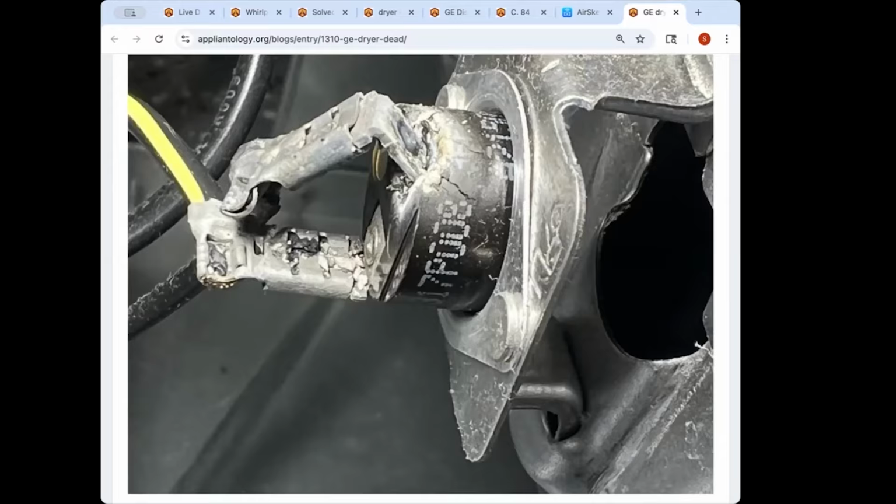And then back to the airflow. I think I have another blog post, interesting enough, about a Bosch dryer. Bosch dryers have the reset thermal fuses on them, and you can reset it and replace that thermal fuse all you want. But in my case, it had so much lint buildup on the heating element, it wasn't drafting air through it. Unless you clean that out, you're just going to keep coming back on that call forever. So sometimes it's not the part, it's not the wires, it's airflow.